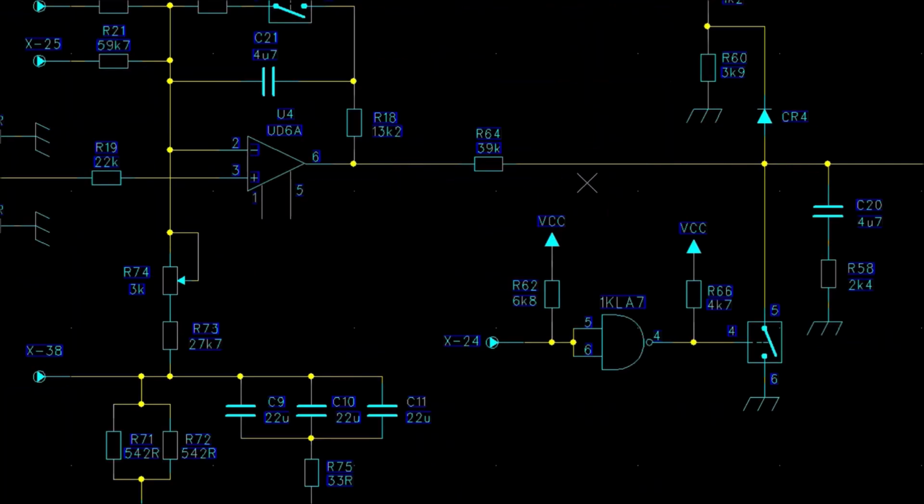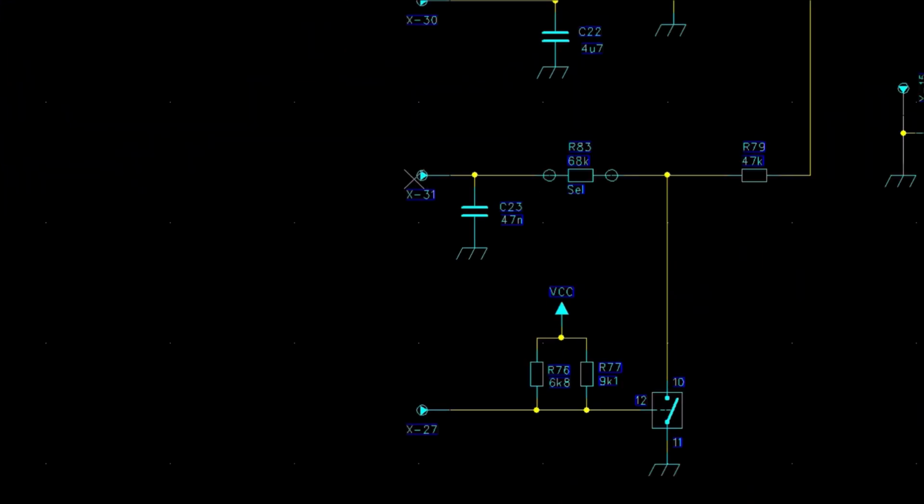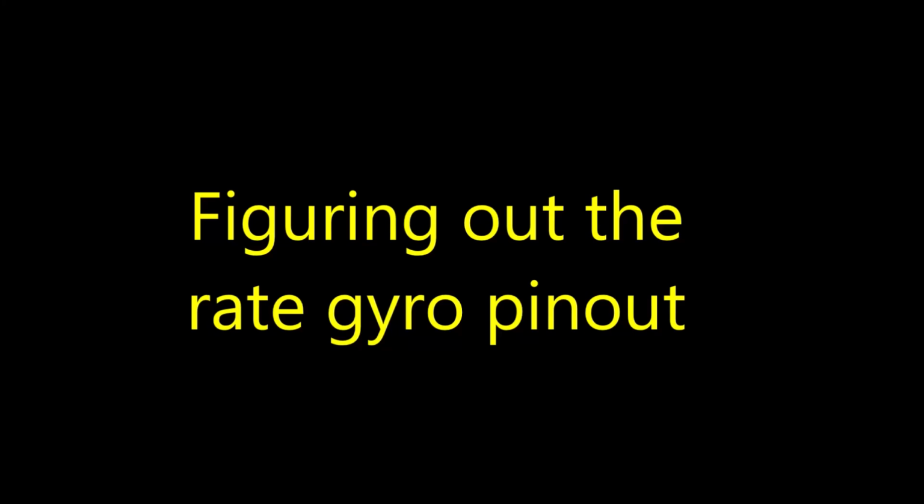The signal is fed to the servo amplifier, so this permits to compensate the rotation of the missile itself. This input is probably connected to the feedback potentiometer using a voltage follower, which is on the other board. I think that this signal is the input signal which permits to set the angle of the antenna in one axis. This signal permits to set the angle to 0. This is a kind of home position. At least it is what I think.